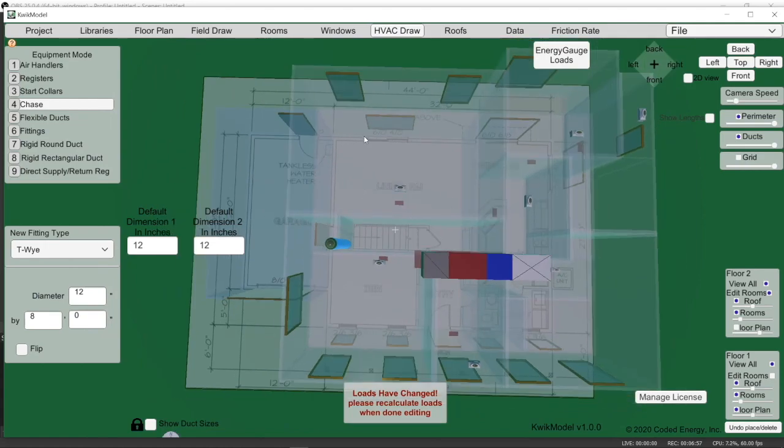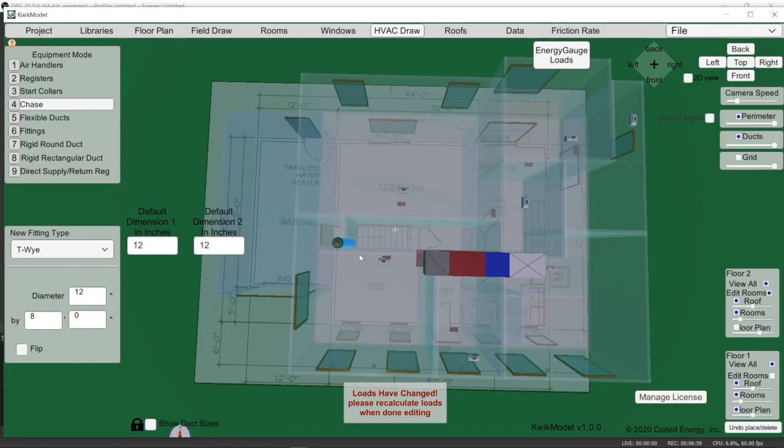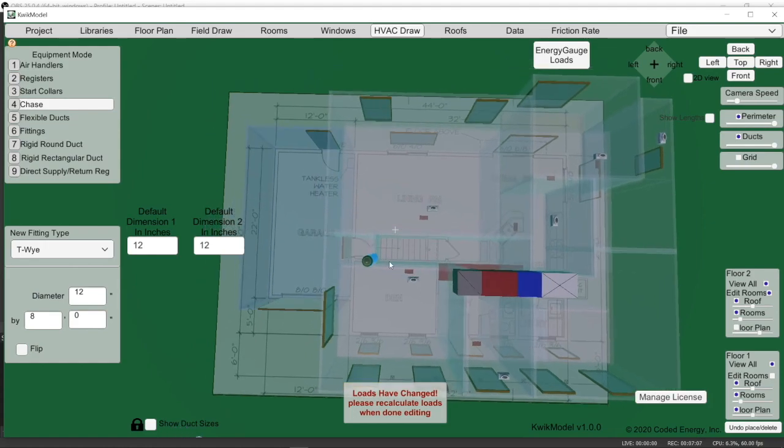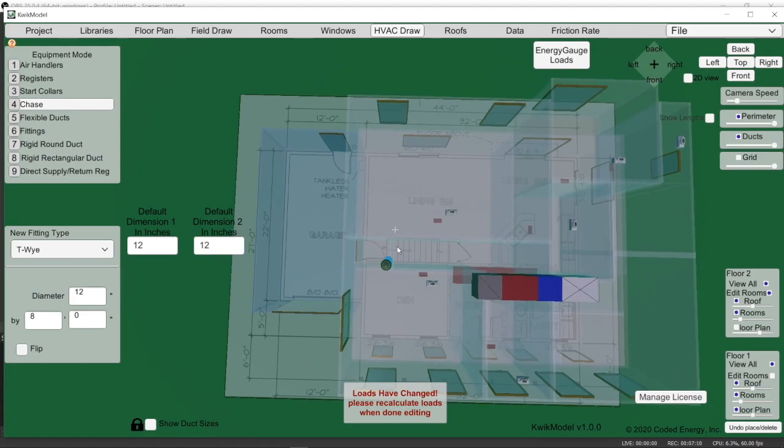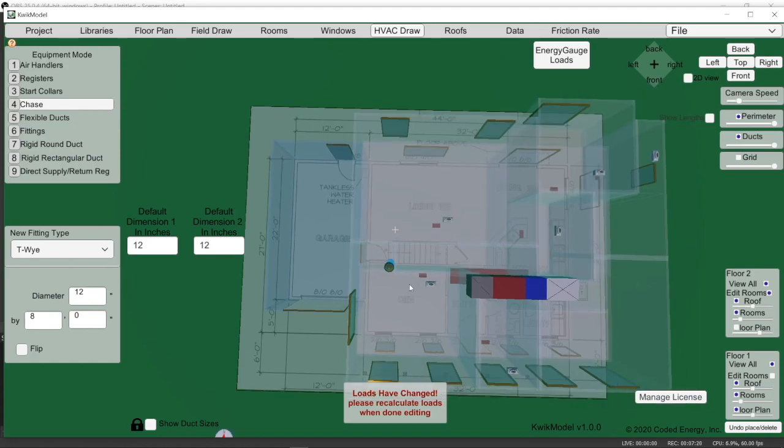So I'm going to assume that the floor joists are going to run front to back. If I get down here, I can run a duct towards the front, and I can also run a duct towards the back. You have to know a little bit about structural. When you have stairs going down, there's usually beams around here, so it's probably going to be difficult to get past this beam unless this little ceiling down here gets dropped.